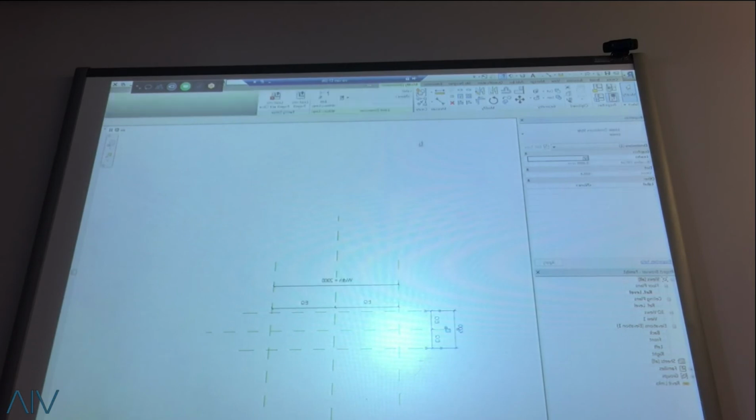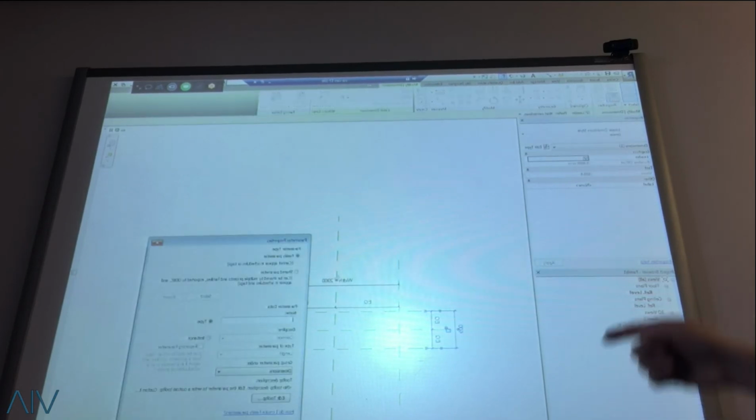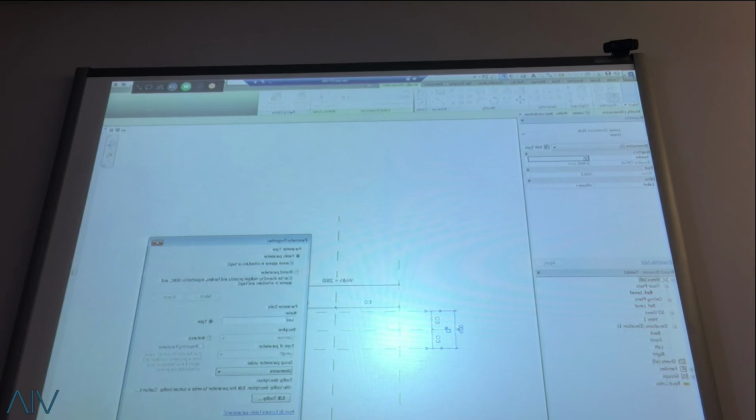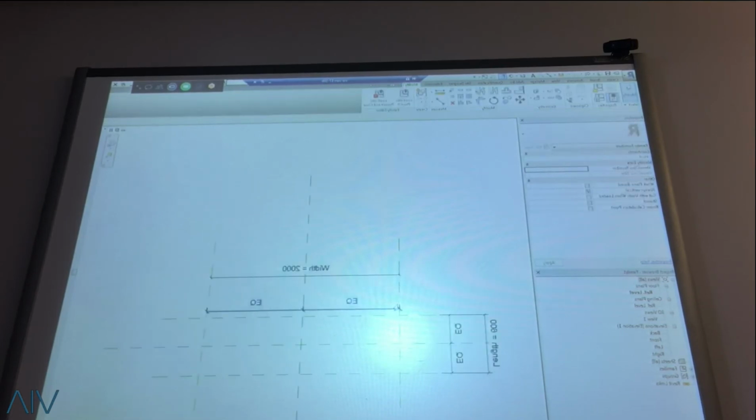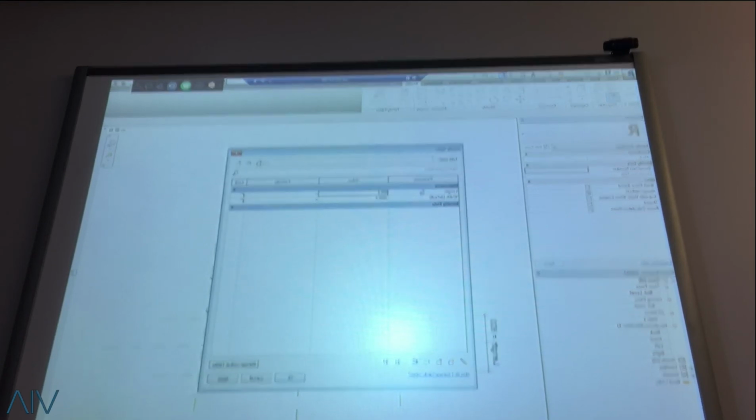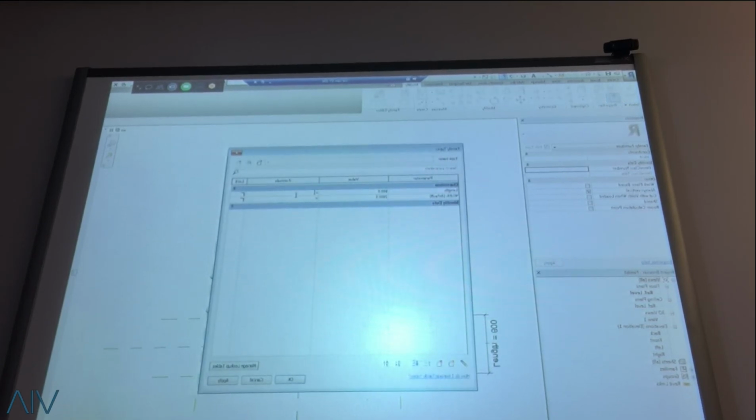Once you have that, then you add a family. I always like to be very descriptive. If it's a length, call it the length. Don't call it an XY. I have a lot of XY. Now, for example, if the width is 200 and you want the length to be half of that, the nicest thing about Revit is that you can put in a formula. You could say, if my width is 200, I want the length to be half of that, and then hit apply.